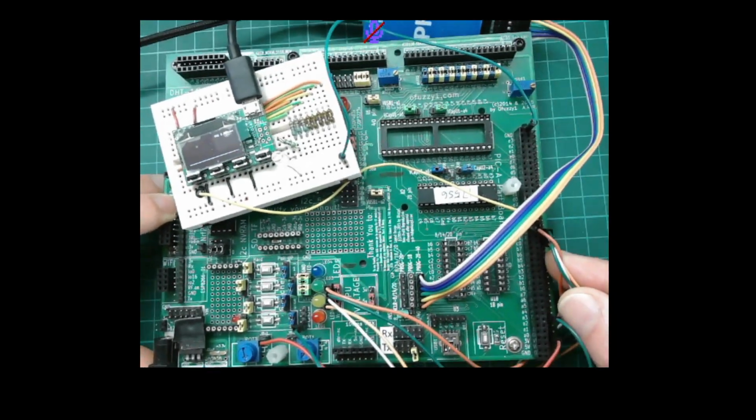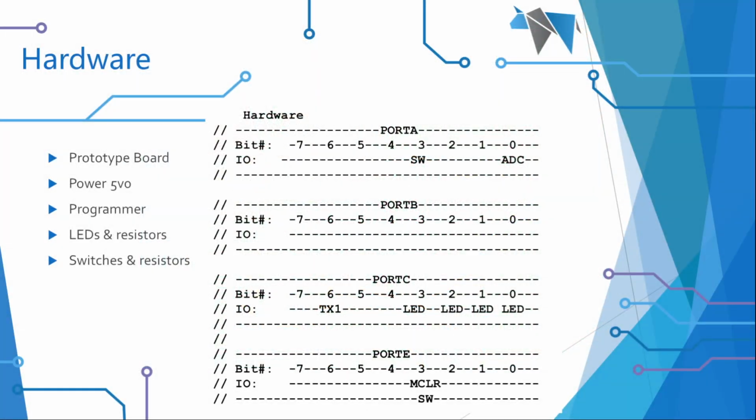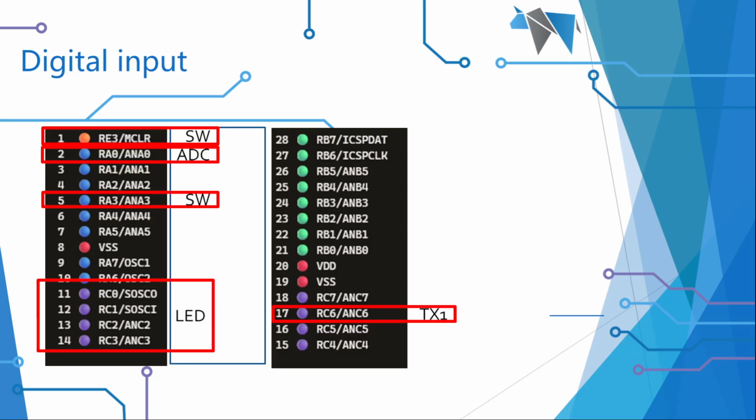Okay, let's just set that all back up. This is the logical layout of the hardware. Essentially, we're going to activate these 4 LEDs, 1, 2, 3, and 4, and I'm sampling one of them with the oscilloscope. It says digital input, but it really shouldn't be digital input. These are digital signals, and I've just laid out where the LEDs are.